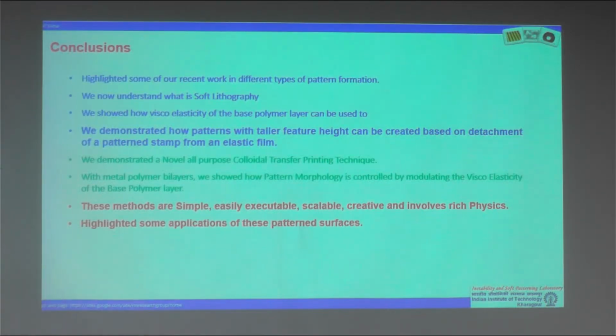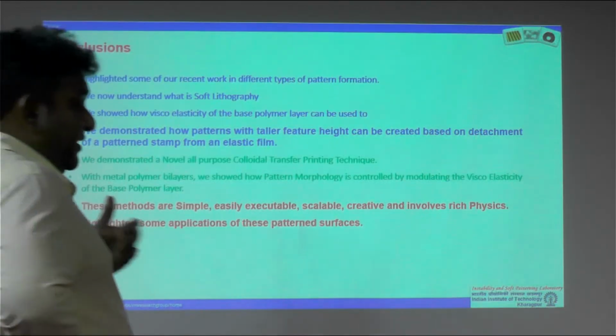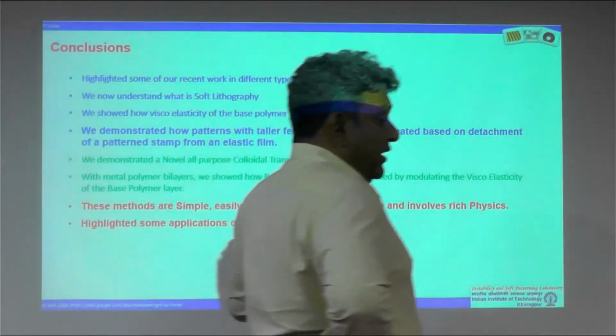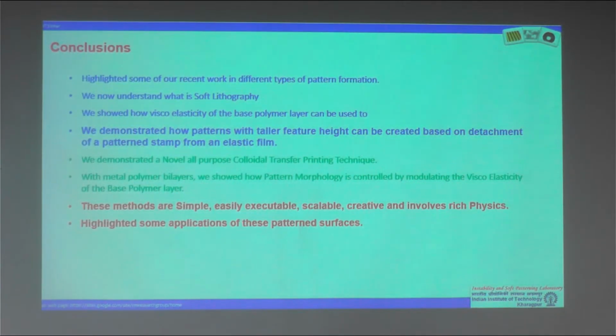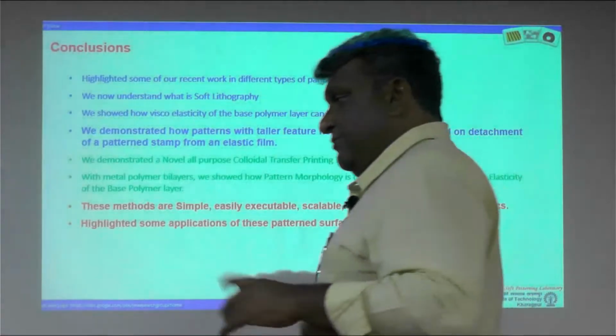And some of these, if you now come across them, will make some sense to you, about molding, micromolding in capillaries, nanoimprint, etc. And then after understanding a bit of it, we realize that soft lithography techniques are capable of creating a perfect negative replica of a stamp, which has to be lithographically fabricated somewhere else.